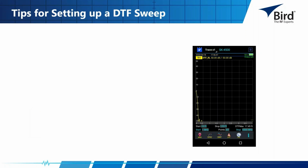And that's pretty much it. How you set up for a distance to fault sweep and how you analyze your sweep. But we have a couple of tips I want to pass along. And maybe those of you that have used your SiteHawk in the past have run into this. Why can't I set a stop distance more than 17.5 feet? And you can see down in the lower right corner, it does give you the distance to fault max.